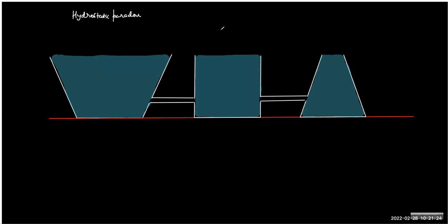So this is called the communicating vessel. Communicating word is, I think, clear to you guys. You know what is communicating. Yes. So if you start pouring liquid in, let's say, the first vessel, the water will rise up to the tube, and the moment you reach the tube level, the water will go to the second, and then will go to the third. And when all three fill up to the same level of the tube, then the water will start rising. But again, it will keep on rising exactly the same for all three. So water will rise by the same level.